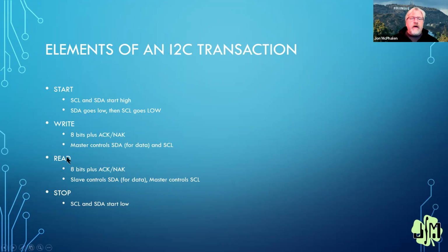Now I have enhancements on these where I can do a block read and a block write, but you'll see that they're just bigger versions of write and read. These are the 4 elemental aspects of I2C. It's a very straightforward, simple communication scheme to handle, and useful because there's a gajillion I2C devices available to us.